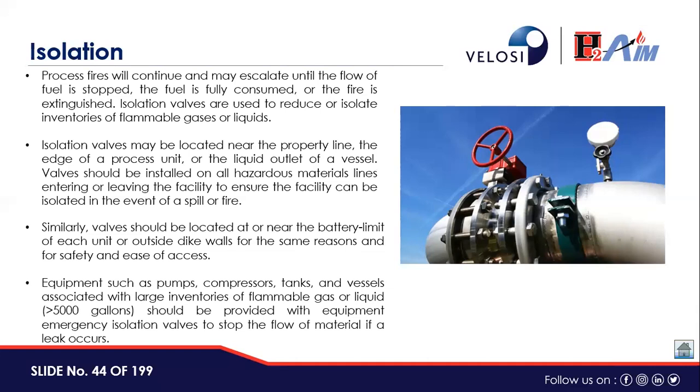There are various kinds of valves used for manual isolation or emergency isolation as well. The other thing is the relief system, which I think is coming next, but relief valves are also there, used to evacuate or remove the fluid from the containment. PSVs, pressure safety valves, and normal blowdown valves are there, and these lead the fluid to the atmosphere or to the flare system as designed.